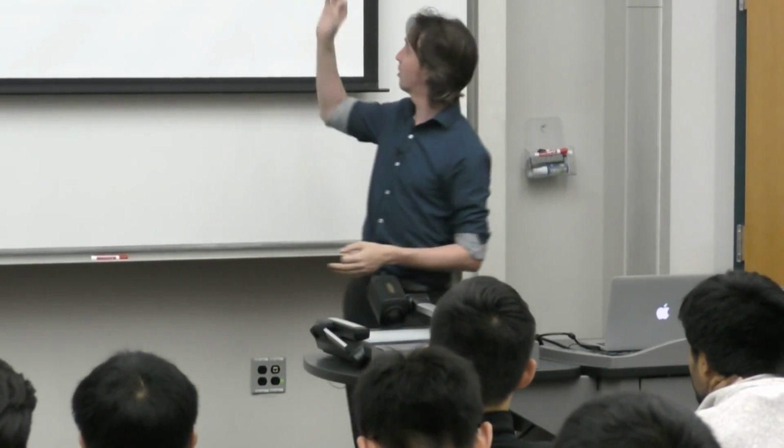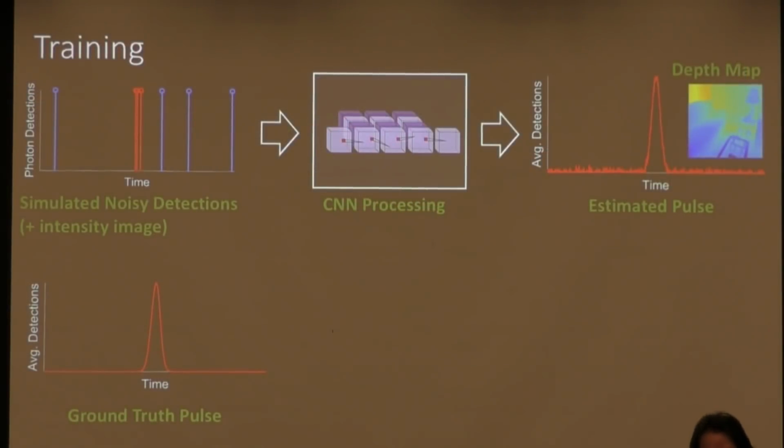So what is the right way to capture shape in that case? Are you trying to look for the object that's through the window, or the shape of the window itself? In this case, we assume that objects are opaque, so we don't deal with that kind of situation. We also assume there's no indirect light, light that's scattering around. We assume it's a simple combination of a pulse like this and a DC component representing our ambient light. If you want to deal with more complex situations, that information is baked into the measurements. It's just a matter of understanding how to pull those details out.